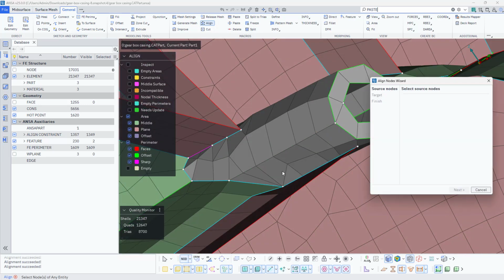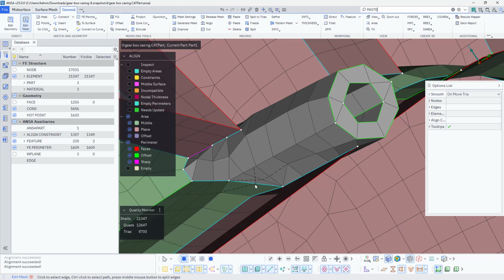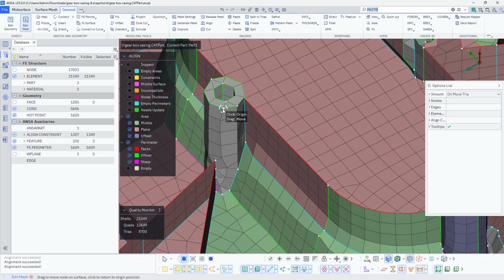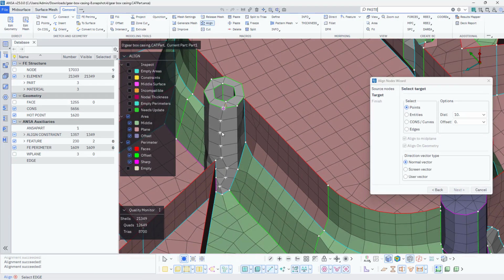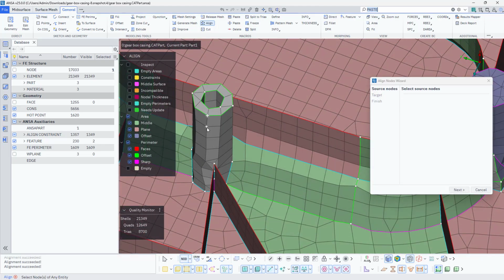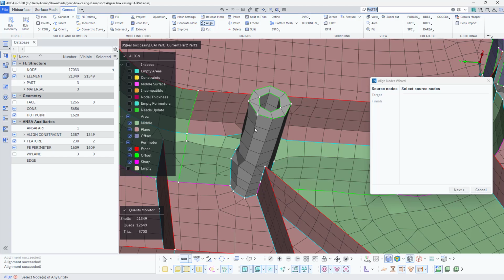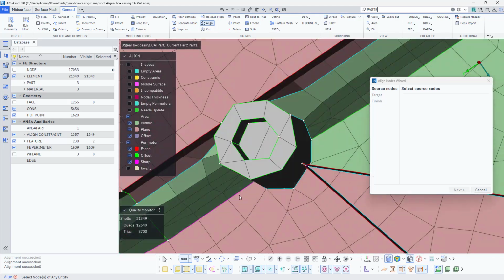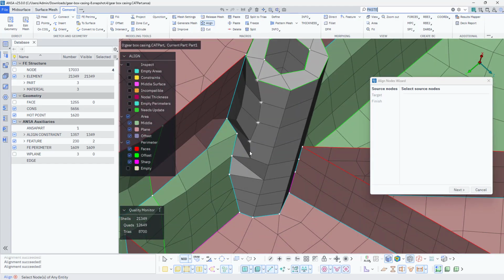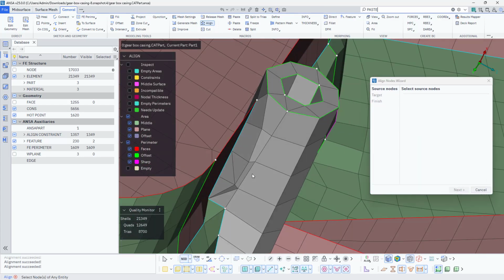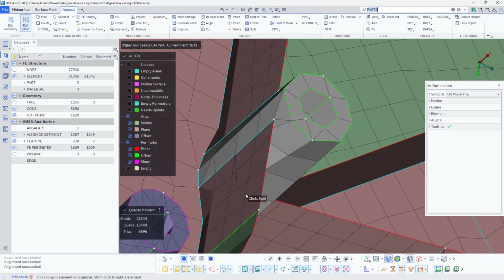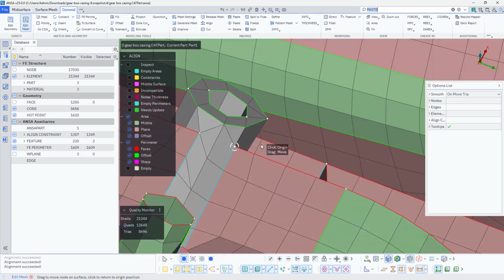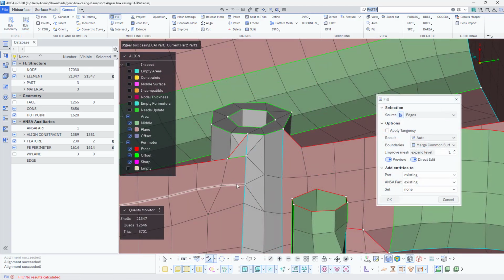Okay, so these mounts which I have created, after doing reconstruct, the mesh will collapse. So this is the big issue. To tackle that, I'm using this manual align tool. Okay, very important. So I could see this region, and here too I'll do the same. Fine. So at this region I'll do the same again. Okay, this is how. Here I'll just simply drag and drop the nodes. Yeah, so this is how I have fixed.